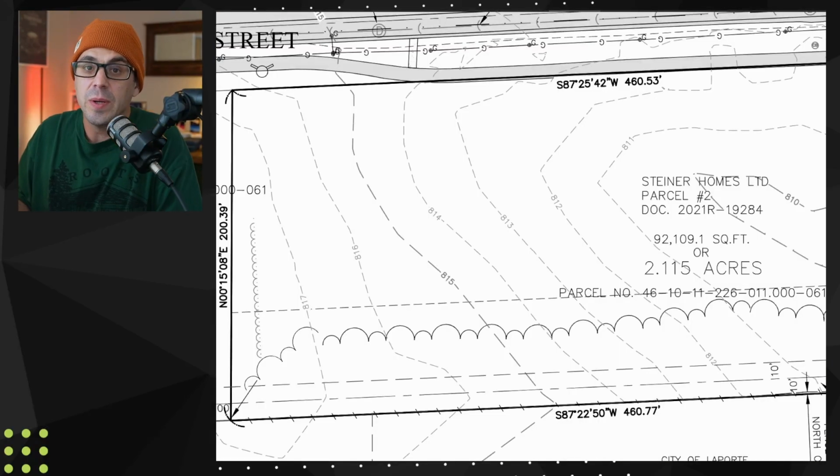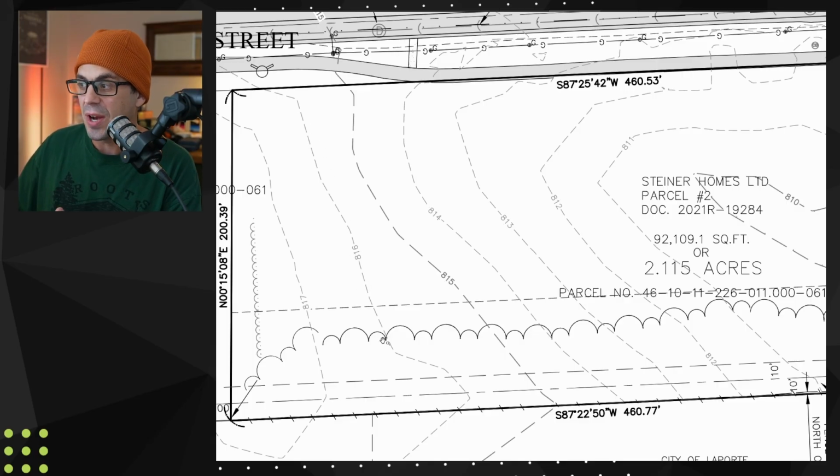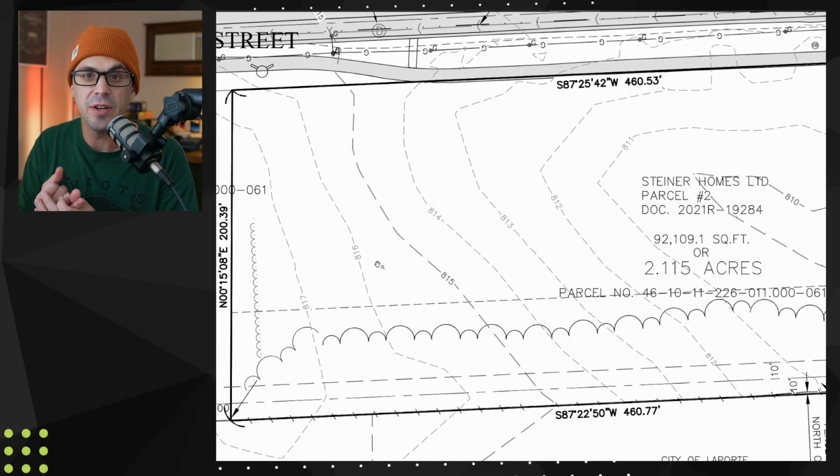Next, for raw land, you're going to need a topographic survey. So this is the survey that shows the elevation profile of your site. Typically in feet, usually lines are every foot, and then you see a more solid line every 5 or 10 feet or so. So this is showing where the grade slopes on your site. Extremely helpful because now we can figure out where does the garage need to be, where is there potential for a daylight or walkout basement, where is too steep where we can't even build, and maybe most importantly, where does your septic field go? The septic field design is completely contingent on your topography. So it's something you really want to get dialed in here.